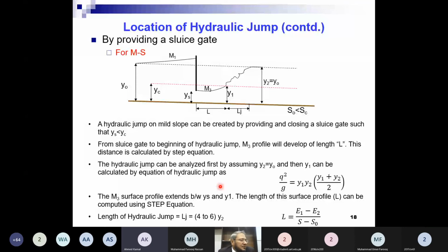It is not. What are you saying? Yeah, this is given that it is a wide rectangular channel, and you can use direct Y also, but as you know, we have computed now, we know the width and we know the depth of flow, so we can exactly compute the hydraulic radius. So if we do not have this information, then we can assume this is the wide rectangular channel, and we can use R is equal to Y.